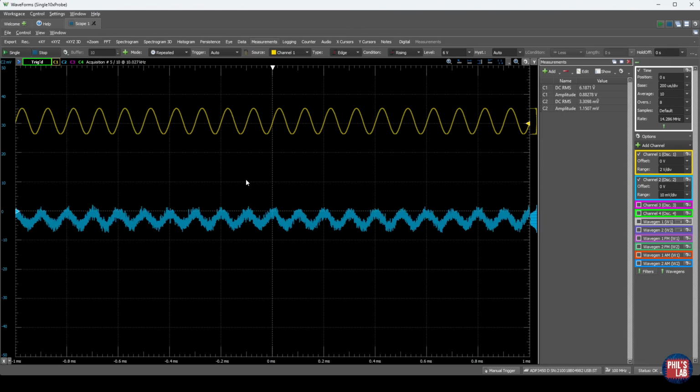And depending on your frequency, depending on the power supply rejection ratio performance of your LDO and your surrounding circuitry, you will get a different noise output for a certain noise input. And this can of course be crucial for your circuit designs. If you're trying to make a low noise analog design or an RF design, you have to keep this in mind. But hopefully that's a nice short visual demonstration of what's actually going on in the time domain.